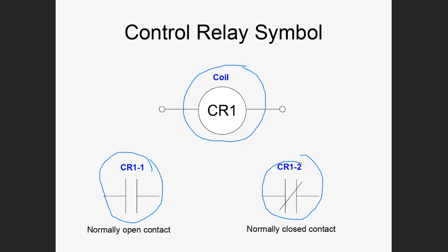In other words, I can use a small amount of current from the PLC to switch a large amount of current in the armature circuit because they're two separate circuits. And that's exactly what we do. So I want to talk about two other types of relays, special relays, used to switch heavy loads.